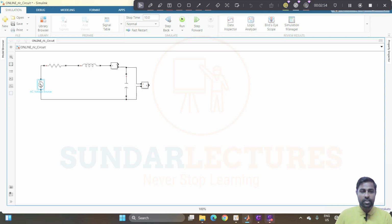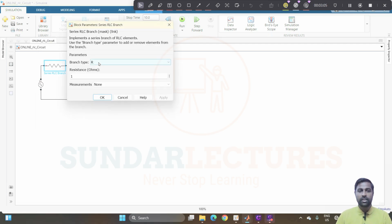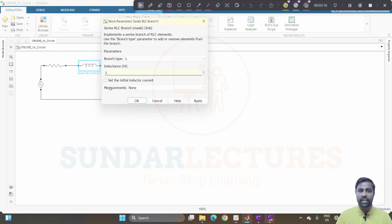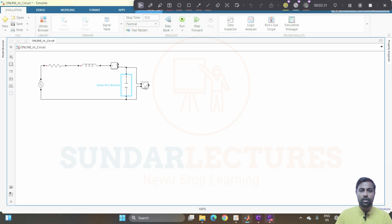That's all. Now go to the AC voltage source. We have amplitude as 10 volts and frequency as 50 hertz. Click OK, and then you see the R block. What is the value of R? First we are going for critically damped, so it is 200 ohms. The L value we have taken as 1 Henry, and the initial current we have taken as 0. For the capacitor it is 100 microfarad, and the initial voltage of the capacitor we have taken as 0.